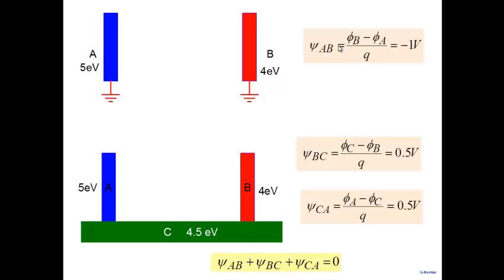And in fact, when you talk about a PN junction and you say there's a built-in voltage, built-in voltage is what? It's a contact potential between a P-type and an N-type. That's what it is. P-type material is one, N-type material is another. You put them into contact, well, you'll get a contact potential. And that's what we call the built-in voltage here. So it's a very, very general result. You always have a contact potential when you put two materials in thermal equilibrium with each other.